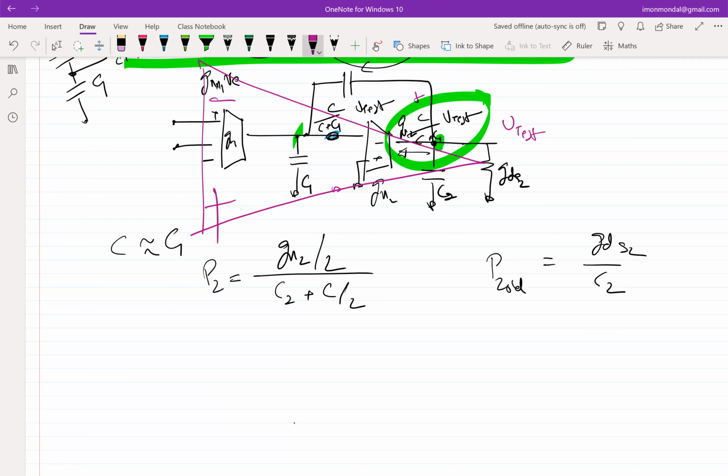Yeah. We'll see. I obviously will not analyze that. I'll just flash it once and see why all of them make sense. This is a very basic structure. But you were right, yes, because then we will be getting higher frequency inputs. Okay, it depends on what you want, right? If you want a very high speed op amp, then it's good. But if you want to ensure that high frequency blockers or disturbances don't come in, then this is bad. So it depends on what you want.